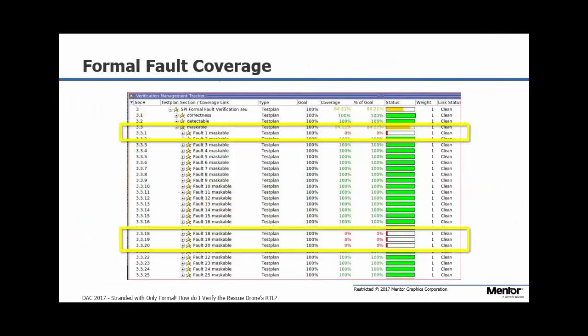Okay, this is all great, but of course, you might have thousands of faults. So you also need an easy way to manage and view the progress of your verification. And so for this, the results of the formal analysis are written out into the coverage database, and the test plan is also generated. And then you can bring up the test plan on the coverage database, and you can quickly visualize the status of your verification and compute your verification metrics. So this is an important step in automating the flow and making it usable for people who aren't formal experts.